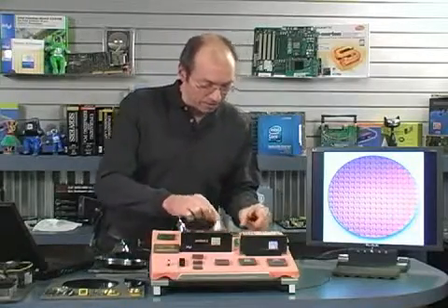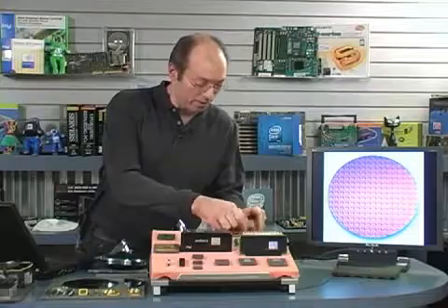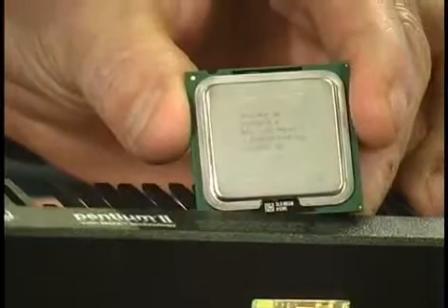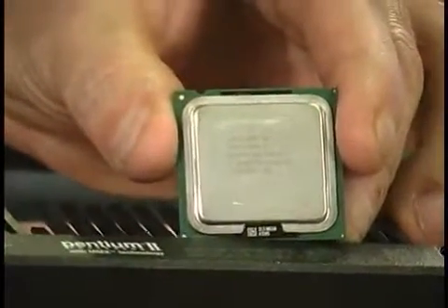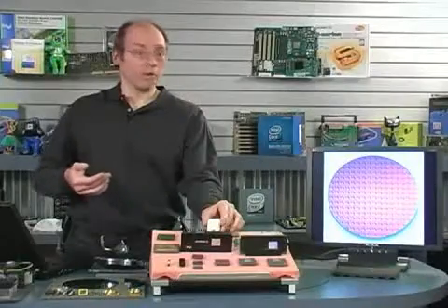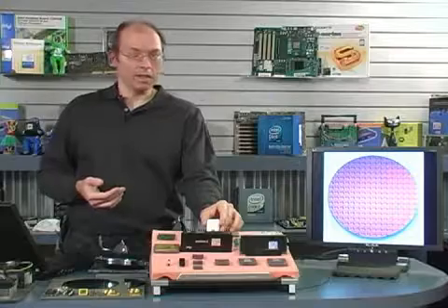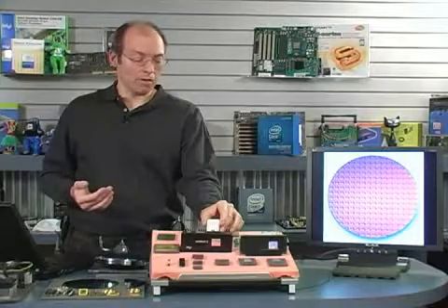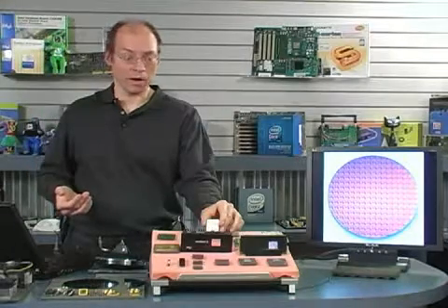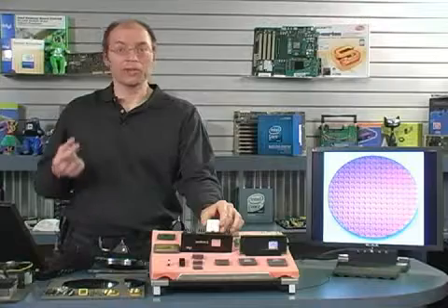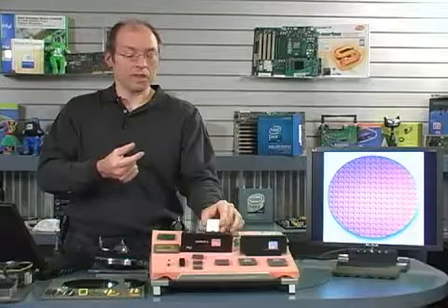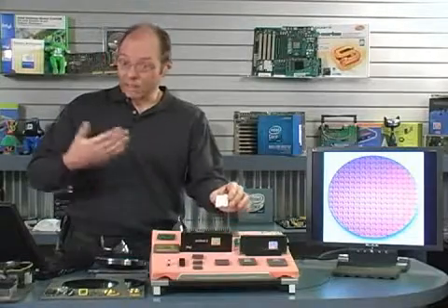Okay, now, continuing on, this is an interesting chip here. This is a Pentium D processor, which was the first dual-core chip. See, up until this time, processing speeds had increased and increased from under 1 megahertz up to over 3 gigahertz. In fact, 3.8, nearly 4 gigahertz. But what was found was that we couldn't keep increasing speeds because heat production was going up tremendously. So rather than increase the raw speed of one chip, they came up with the idea of putting multiple chips in the single processor package and basically have multiprocessing.